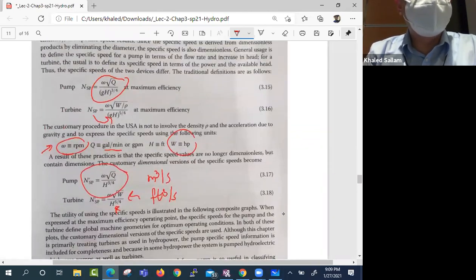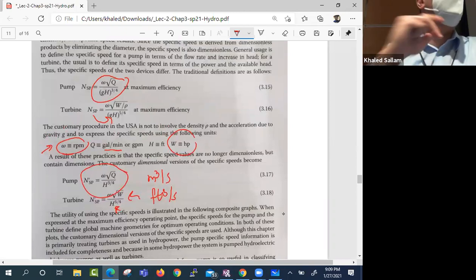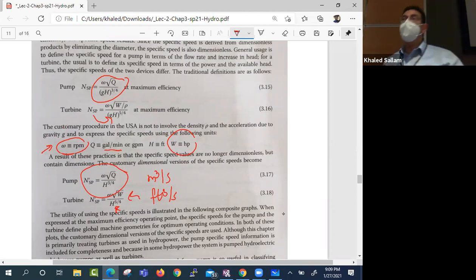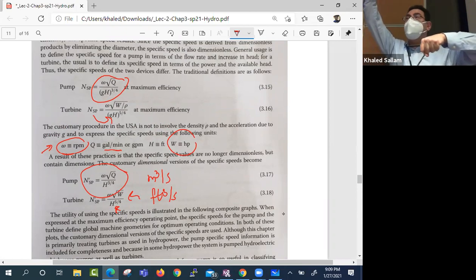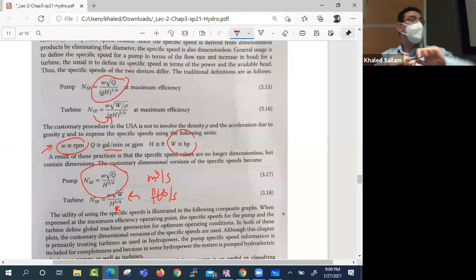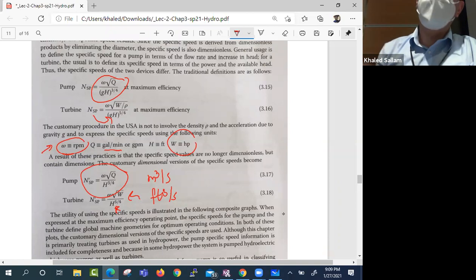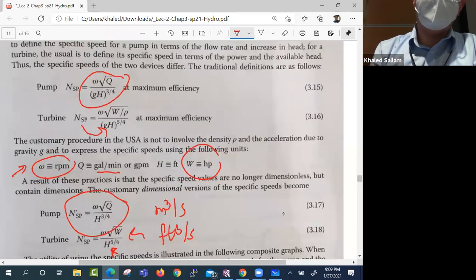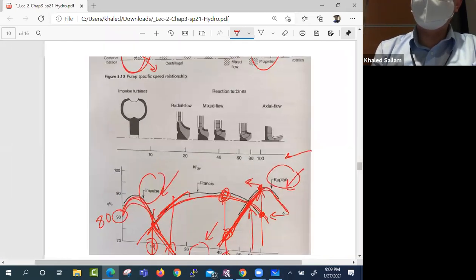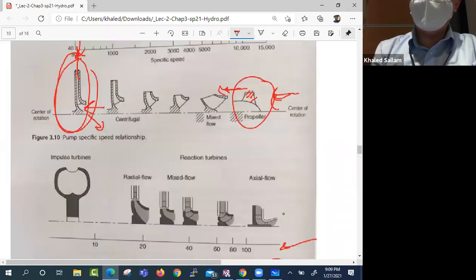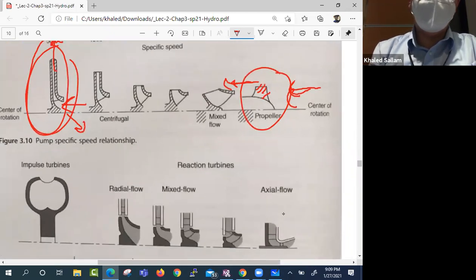And the same thing for the turbine, for the pump, by the way. Remember the hydro storage system that I told you, where you have a turbine and a pump on the same shaft, and when you have extra power, the pump works and takes the water to the dam or the lake, and when you need work, you run the water the other way in the pipe and the turbine works. So you can make the pump the same way. You can calculate the specific speed for the pump, and you go to that chart for the pumps, and you basically tell yourself which pump I should use.